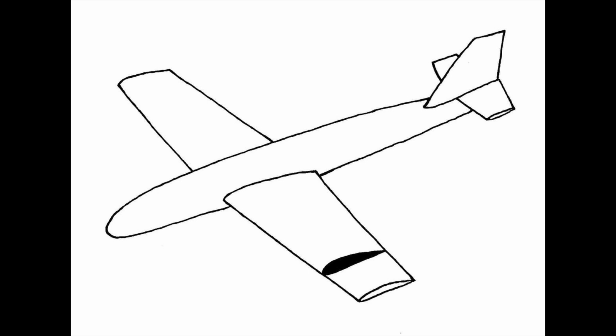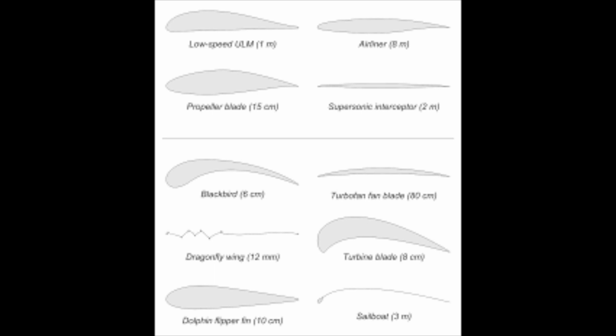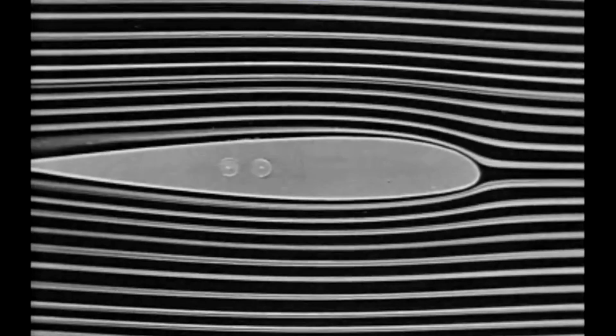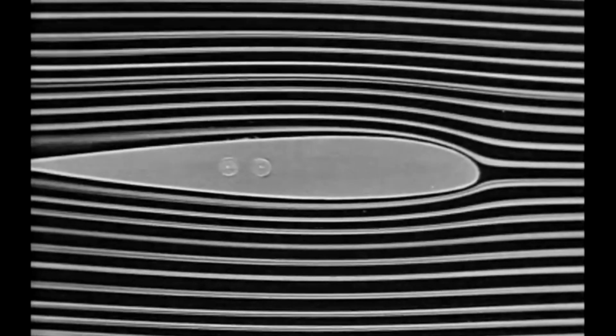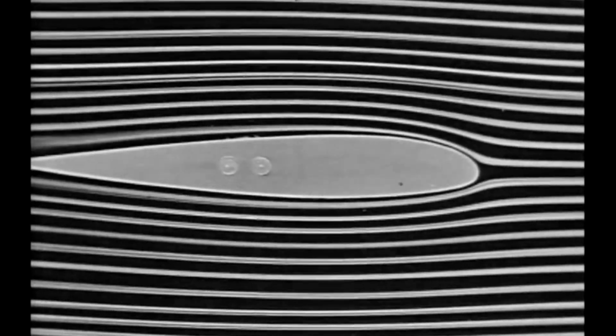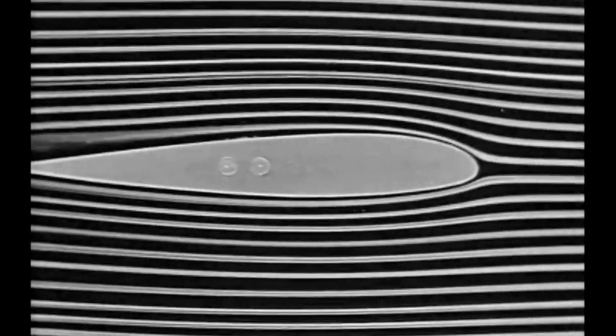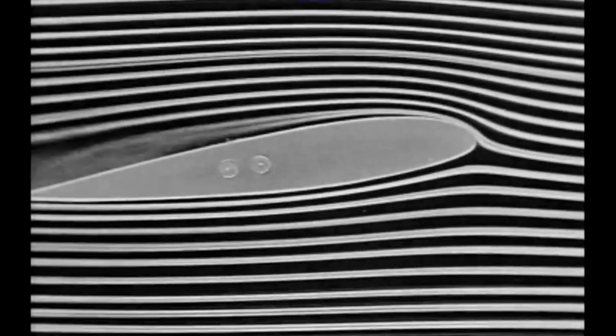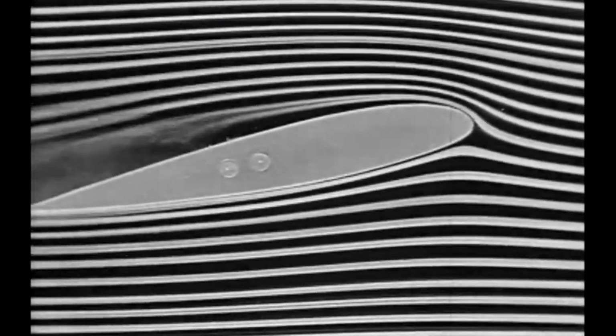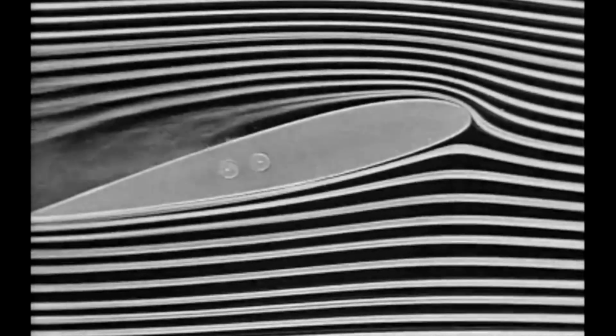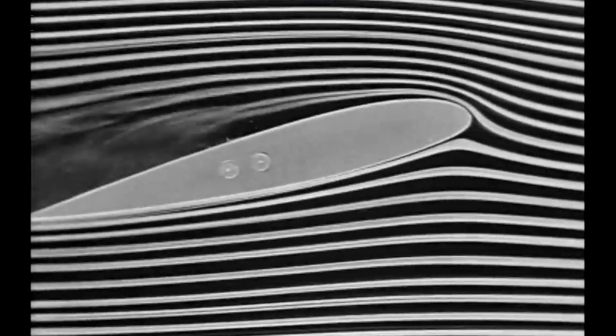Airfoils are two-dimensional cross-sections of wings. Basically, they're arced in the front, and they converge to a point at the trailing end. These airfoil sections are used to manipulate the flow such that it produces lift for us. The way an airfoil manipulates the flow around it can be best described by using Newton's third law of motion and the Bernoulli principle. As the airfoil travels through the medium, the airfoil deflects the flow downwards, and as by Newton's third law of motion, that airflow will have an equal and opposite reaction upwards, pushing the airfoil up. That's a very big picture understanding of how lift is being produced.